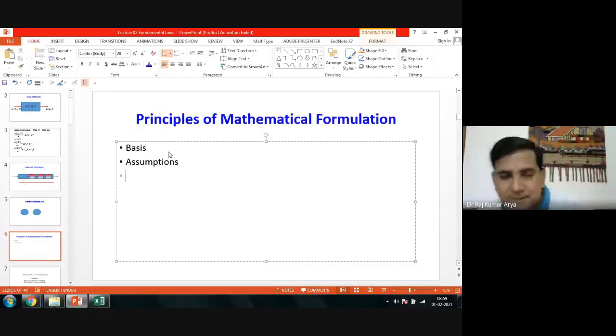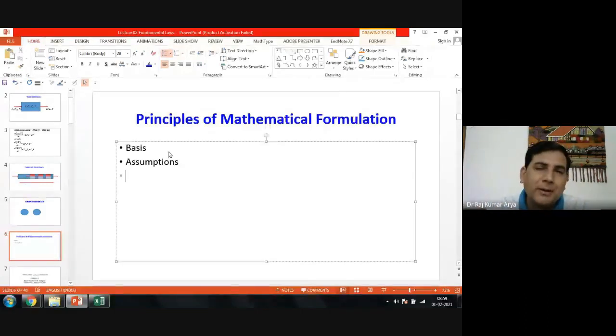So realistic assumptions simplify the problem, staying close to practical values, and that comes from practice. It's not like you can neglect anything. No, it's not like that. Just like a PFR: if you are talking about a plug flow reactor, and let's say the radius of the reactor is not very large, most of the time you just consider no variation along the radial direction, correct?